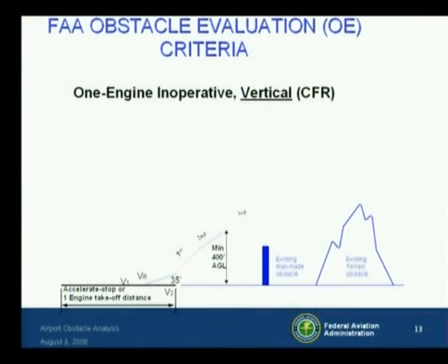So let's look at a picture of some of this stuff. We start with the runway and continue through the 3 climb segments. The airplane accelerates through V1, rotates at VR, and then must reach V2 before it hits 35 feet above the takeoff surface.